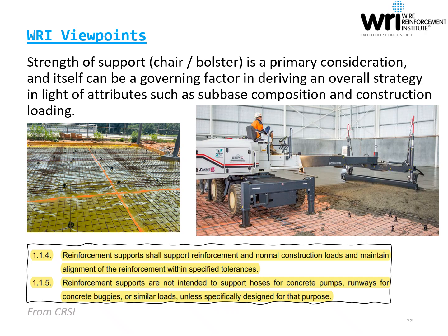Regarding the strength of the supports themselves, CRSI does a fantastic job of defining expectations and requirements in its RB4.1 standard. An excerpt is shown here that references this type of information. The point here is that the integrity and reliability of the supports themselves could very well govern over the attributes of the supported reinforcement. There is no boilerplate solution, and placing contractors need to be aware of the need for bespoke support solutions to ensure that the combined system, both reinforcement and the reinforcement supports, act concurrently in a way that achieves conforming results.